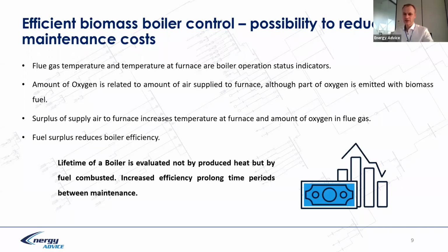this optimization is tricky. We understand this, because if your boiler mode is quite dynamic, I mean there is a dynamic change in heat demand and the calorific value of the fuel changes dynamically during the day, the optimization is required, and you always have surplus oxygen.